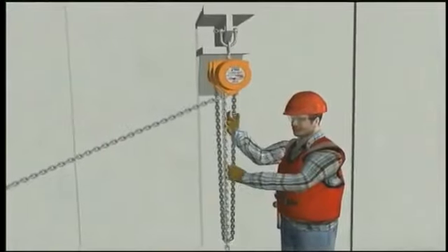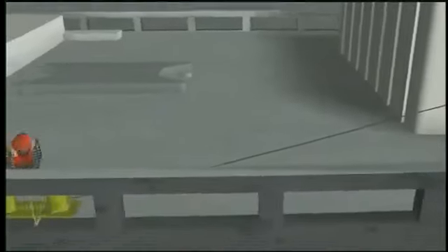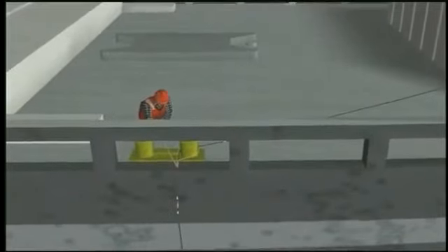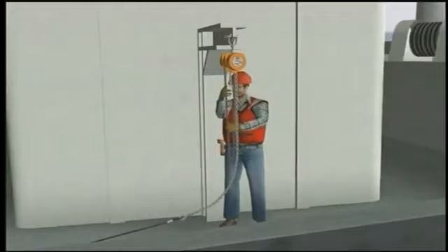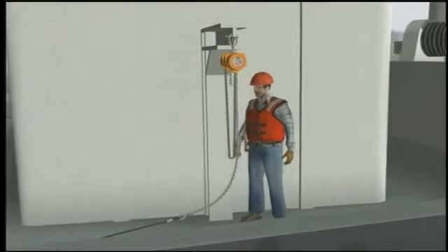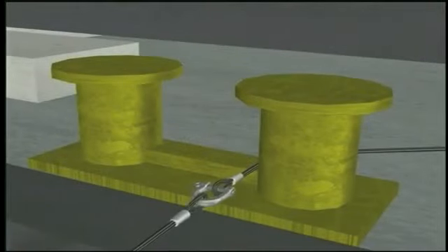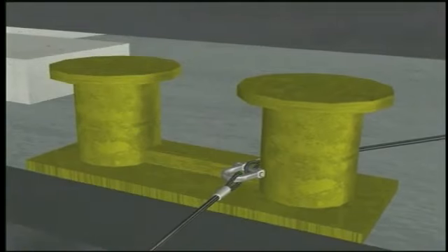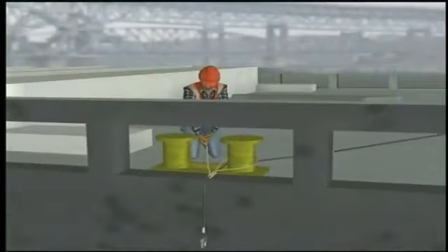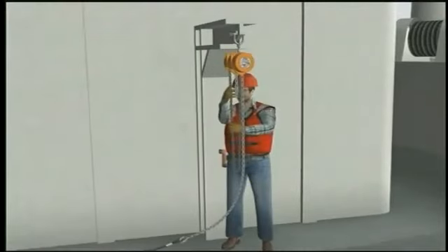As the chainfall pulled its maximum distance, the sling assembly was secured to the bit by manila rope used as a stopper. The chainfall was then slackened so that the chainfall hook could be attached to the next sling shackle through the bit. As the second sling was pulled by the chainfall, the sling shackle got hung up on the bit. The sling assembly was secured with a manila rope stopper, and then the chainfall was backed off.